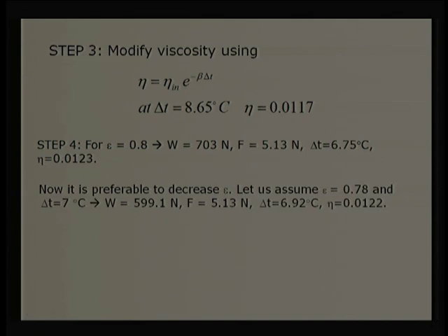Or we say if you want to go for the finite difference method, this design is going to give reliable results. Or if we assume that load carrying capacity estimated by short bearing will be slightly higher, then we can think about 0.7 also, 0.79 also, which will give roughly maybe say around 640 Newton load capacity. Applied load is only 600, we say okay, that is fine for us, we can go ahead. So, this is how we do calculation.